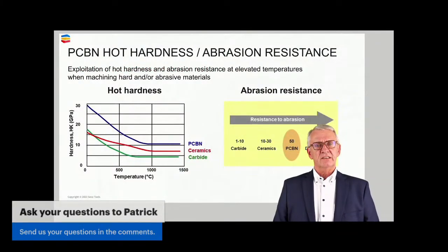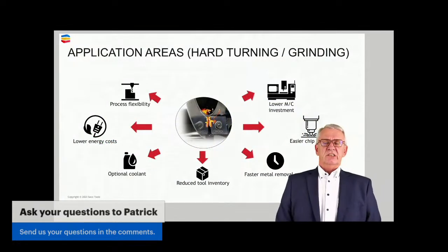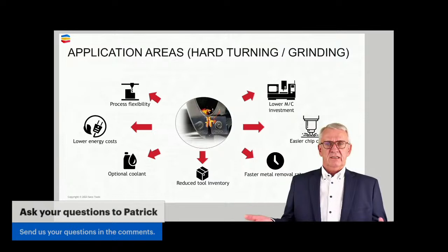Hot hardness, the hardness it has and the ability to keep that hardness at higher temperatures, makes PCBN specific, and abrasion resistance, the hardness in general. It's the material that challenges grinding in nearly every application.